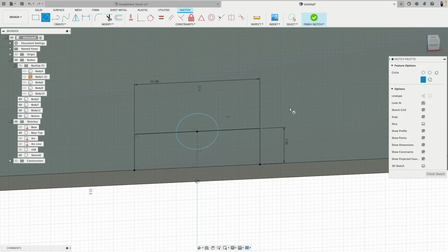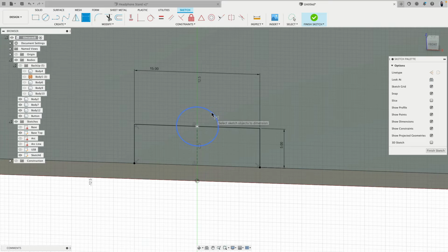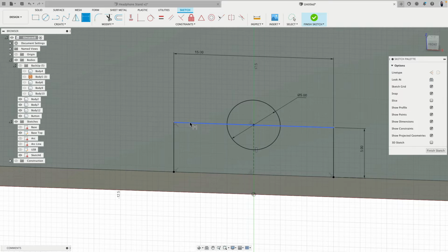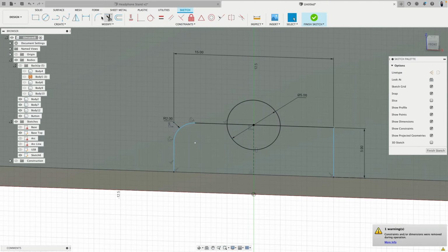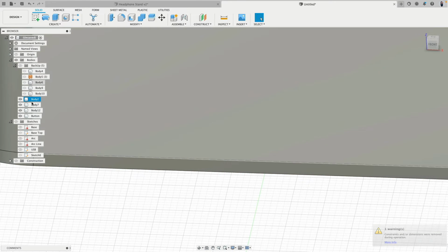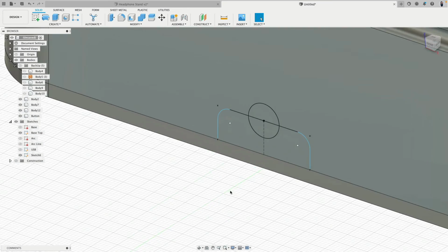Then we can give this a nice circle at the center, 5 millimeters. We could round the edges here now, or do this later with the edge rounding fillet command. In this case, to make life a tick easier, I'm doing this already right inside the sketch environment. I know very often I say, try not to do all this extra work when not necessary. But in this case, it will make the task at hand a tick easier.